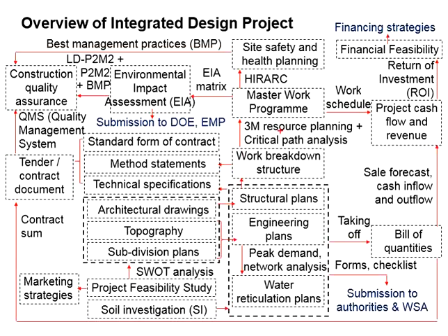At the same time, you look into the master work program in terms of the work schedules, so that you can forecast the progress of the work over times. Based on the cost bid by the contractor, let's say, knowing when the work shall be completed, associated to every single item of the work, then you can easily forecast the cash outflow. That means the amount of costs involved at different stages of the project, completing different tasks of the project.